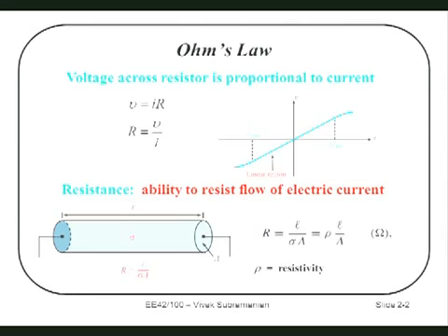So when they make these carbon films, to vary the resistance by a small amount, they just change the dimensions. In fact, if you open up one of those resistors, for really high resistances, it'll actually be a little serpentine. It won't be a straight line. It'll be sort of really squiggly. But if they want to have a big change in resistance, they just change the material. This value, rho, or this value, sigma, tends to be a property of the material.